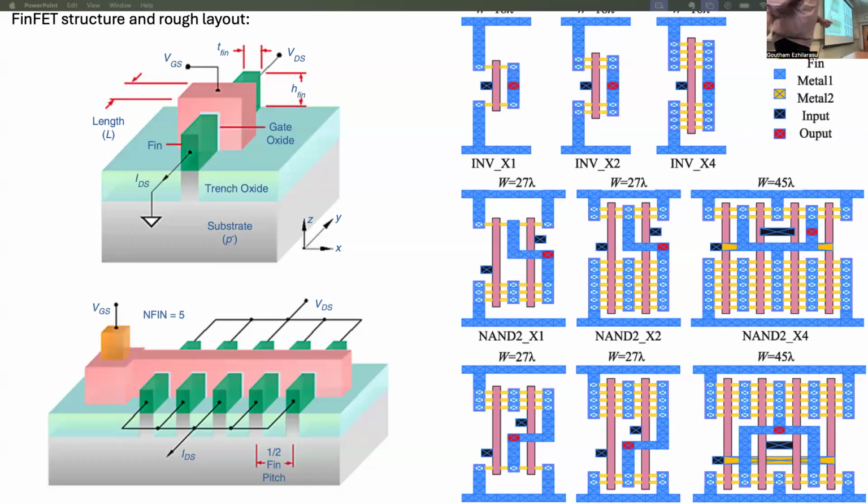So if you look at the circuit, this inverter is just a PMOS and an NMOS. And this is the input. And then the output goes to some other stage, right? But the entire stage can just be modeled as some capacitor. So what it's actually doing is either charging this capacitor to the supply or discharging the capacitor to ground, right?